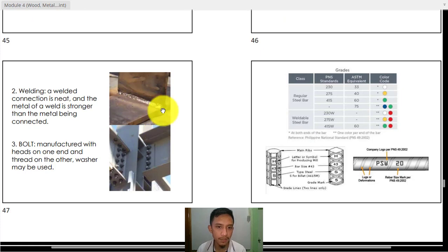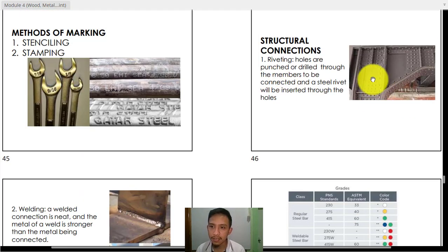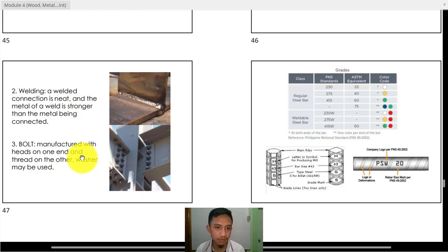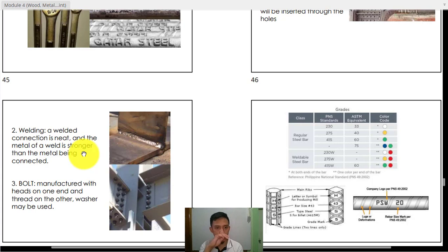So this comes in different types, of course. The rivet needs to conform with the strength of the connection. That's why your connections are designed based on the number of bolts, number of holes, and the thickness of the members being connected, and that will require a certain strength of the rivets. The same with the bolts. So we also have grades for the bolts and rivets, and of course your welding. We have these types of welding and grades of welding also, because of course the connection is critical, especially on a structural member.